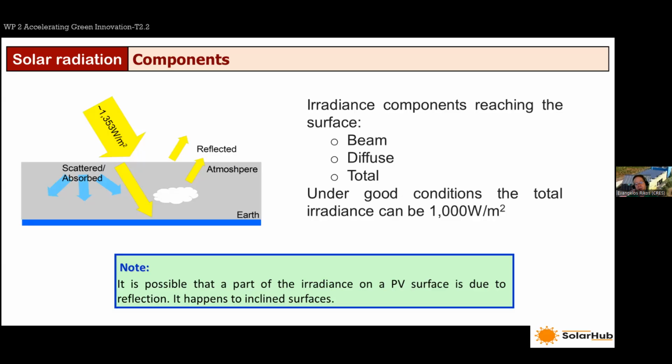But there is still the option of outdoor measurements. I repeat that one can measure a panel outside, but in any case, they will always have to recalculate the results based on standard test conditions. That's the most important thing. So whatever you measure outside, you always have to recalculate it afterwards. Okay, all right. Thank you. Thank you so much.